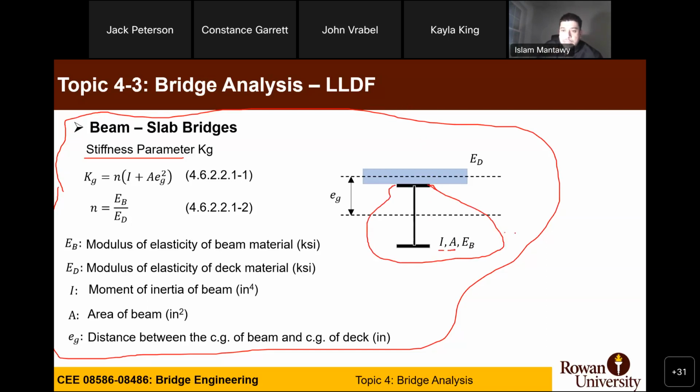Which homework was that? Yeah, we did it for assignment 3, lecture 4.1, the first part. If you have a steel girder, you can come up with a table to calculate the thickness of each plate, width of each plate, and the areas, and complete the table to get the inertia and the area, correct?